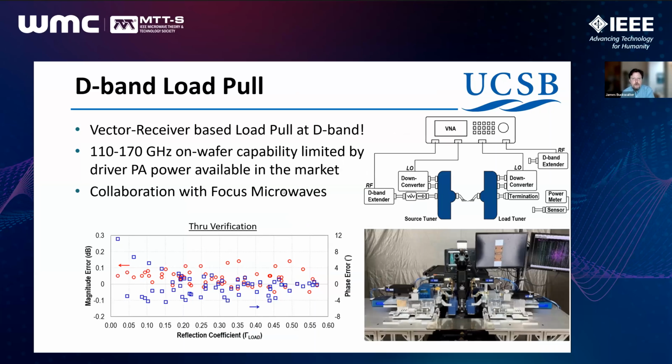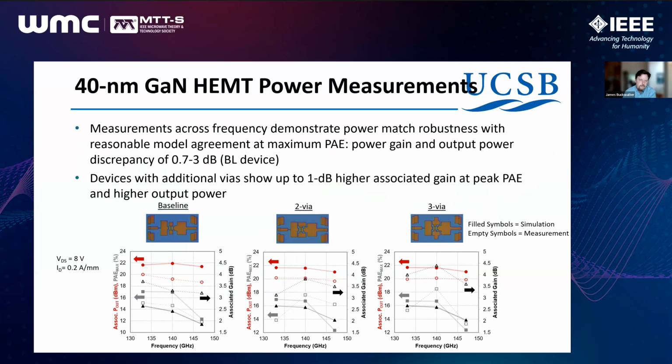We were able to get some load pull access thanks to Focus Microwave. So we were able to get some input based on load pull, and we used this in later work on indium phosphide HBTs to help determine what the best load line conditions were. So when you can get access to a load pull, this could also be part of the model development using a neural network. But at first, we started out developing this around the large signal and the IV characteristic and the S parameter characteristics of the devices.